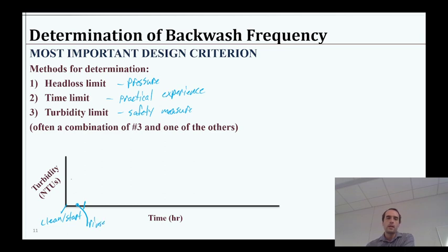You're going to be rinsing or ripening, and your turbidity is probably going to be above some limit here. And then it'll start decreasing. So if that's in like 20 minutes, I'll sketch out the typical cycle time a little more clearly in a minute. But just to give you a picture here, if that's our rinsing stage, then we expect there to